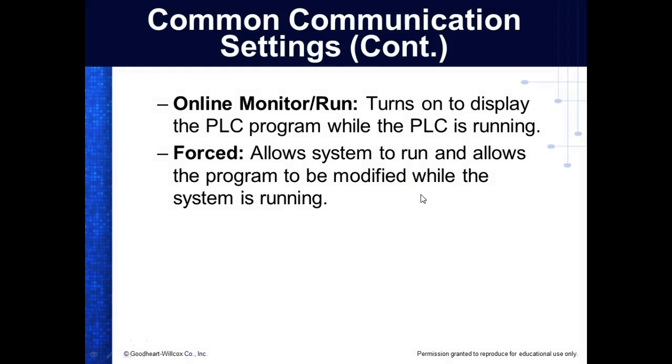Online monitor, that's what we're talking about. With Siemens, when you switch it to online, when you upload it and it asks if you want to go online, what it'll automatically do is go into the monitor mode. With the Siemens PLCs' application, you have to tell it to monitor. Force. What do you think force allows us to do?